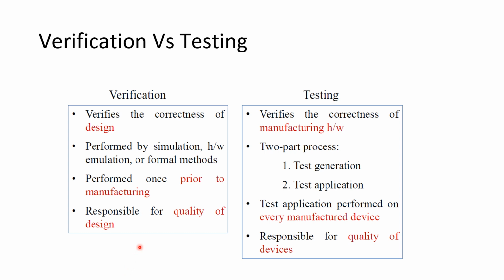What are the major differences between verification and testing? Both are very different, and please understand this. This is a very important concept you should remember throughout your life, the same in software, hardware systems, wherever you go. Verification is what we do pre-silicon, and testing or validation is what we do post-silicon.